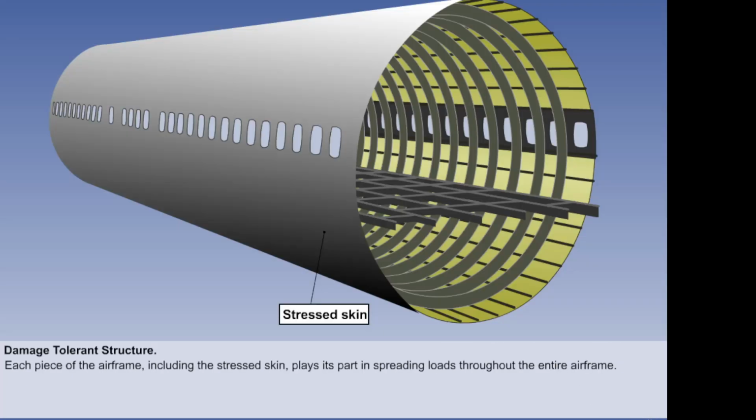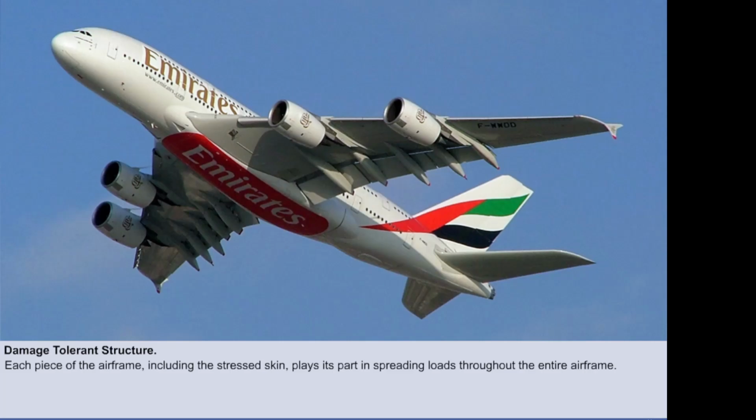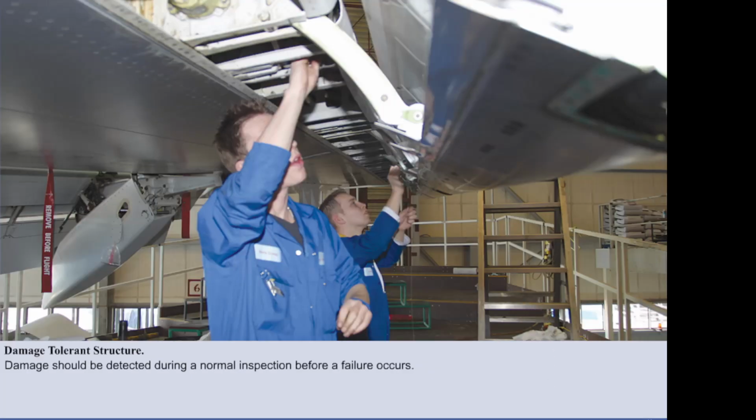Modern concepts of aircraft design employ the stressed skin style of construction, where each piece of the airframe, including the stressed skin, plays its part in spreading loads throughout the entire airframe and is tolerant to a certain amount of damage. These damage-tolerant structures eliminate the extra structural members needed in a fail-safe design by spreading the loading of a particular structure over a larger area. Damage-tolerant structures are designed to withstand a certain amount of damage, which again should be detected during the normal inspection cycle before a failure occurs.